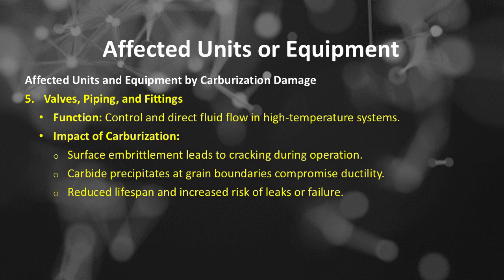Number 5 is valves, piping, and fittings. Function: control and direct fluid flow in high-temperature systems. Impact of carburization: surface embrittlement leads to cracking during operation. Carbide precipitates at grain boundaries compromise ductility, reducing lifespan and increasing the risk of leaks or failure.